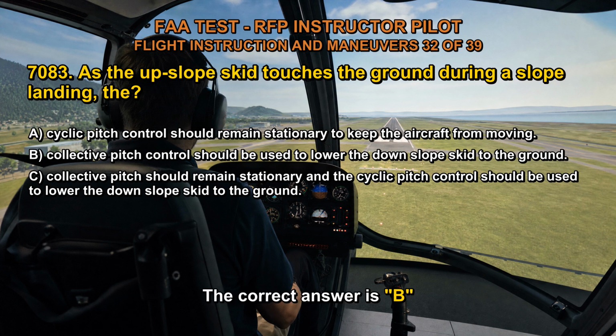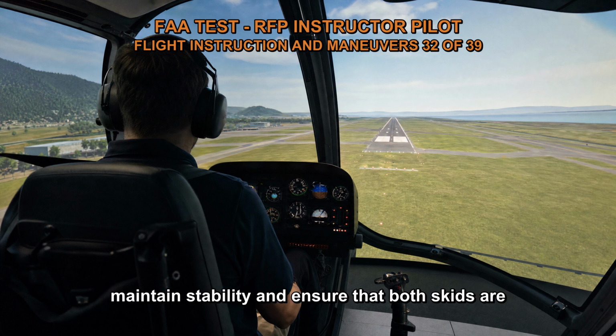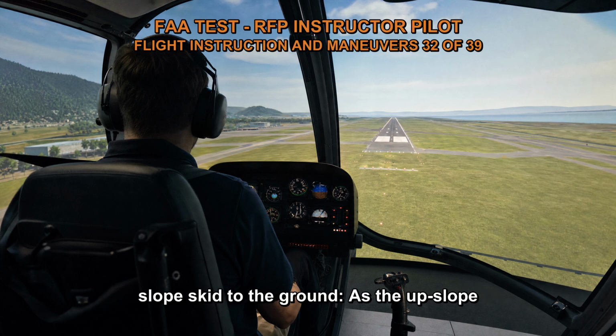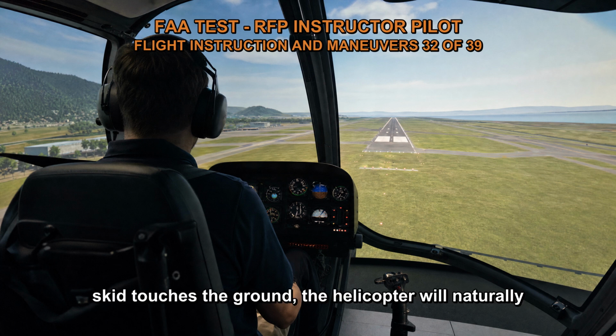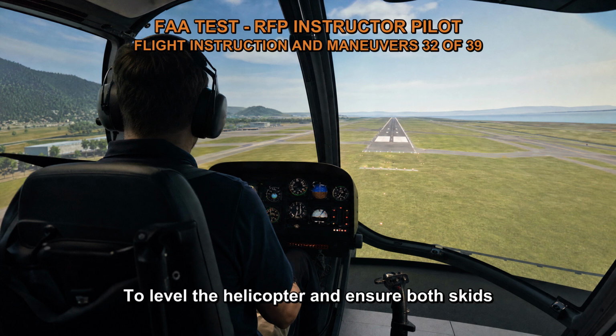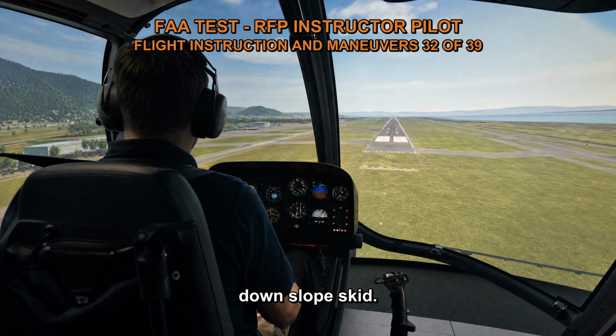The correct answer is B. During a slope landing, it is important to maintain stability and ensure that both skids are in contact with the ground. The appropriate action to take: lower the downslope skid to the ground. As the upslope skid touches the ground, the helicopter will naturally begin to tilt towards the downslope side. To level the helicopter and ensure both skids are on the ground, the pilot should use the collective pitch control to gradually lower the downslope skid.